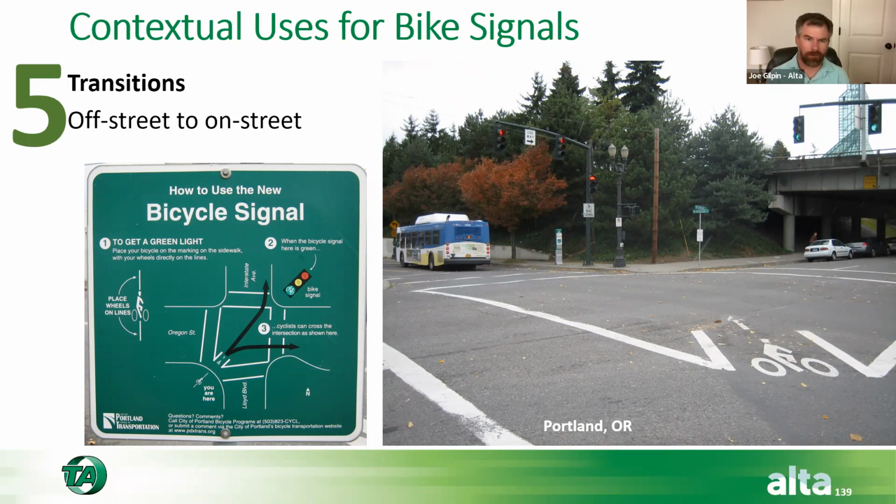Because most cities and other folks will use Synchro to model their traffic. And what's bad about Synchro is that it has to assume that this phase is going to be called every cycle in order for it to make sense to the software. So there's no way for you to say, oh, we're going to have 15 bikes an hour and you're going to call this every 5th cycle through that time. We can't do that.